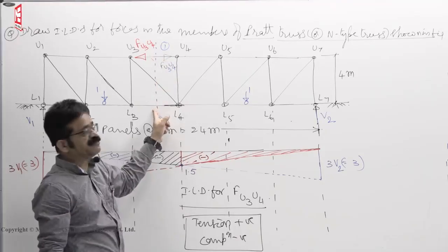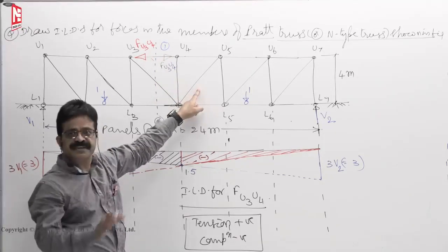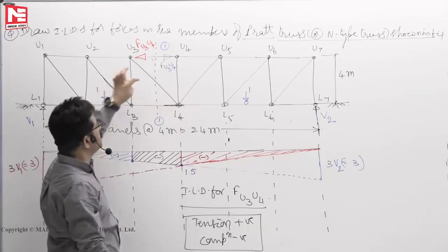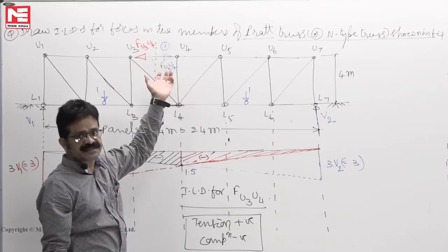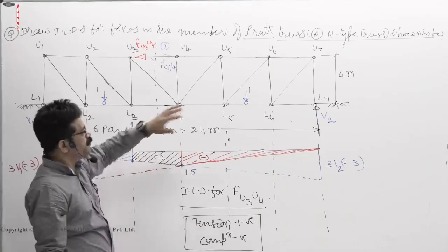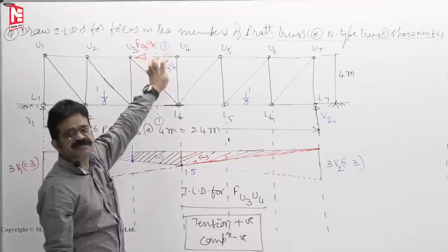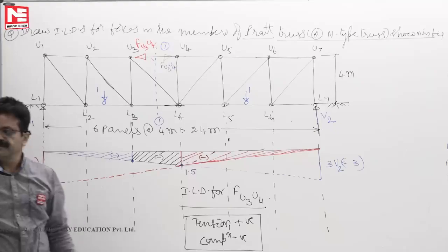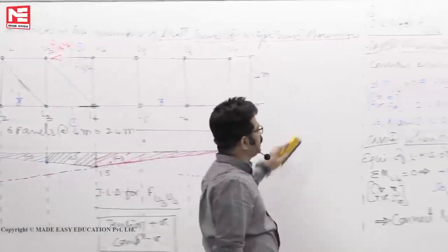This is for tension member. These members are subjected to reversal of stresses. For one portion compression, another portion it can be tension. Like that. So reversal of stresses you have to design. We will see that point. Now this is a pure compression member. So that observation will write here.